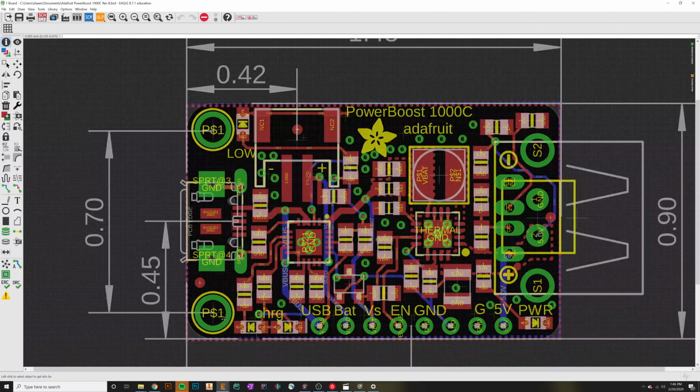Alright, so now the last thing I have to do is simply hit connect, and then I need to tell it which pin corresponds to what. So pin 1 was this pin right here, 2, 3, 4, 5, all the way down. So if we look back at this, it's telling me that pin 1 is USB. So I'm going to select USB and then 1 and hit connect, not OK.